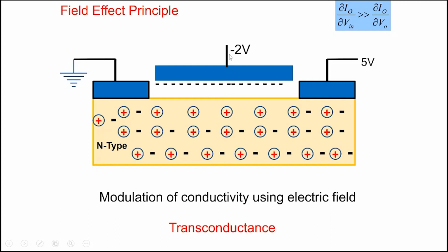And we can also see transconductance being there. The voltage is being applied between these two pairs of terminals. If we take this as a reference, the voltage is being applied between these two, and is altering the current flowing between these two pairs of terminals here, right? So the current flowing here in this particular terminal is being controlled by the voltage being applied here. That's the transconductance feature here. And of course, we need to show that for this to act as a transistor, the current flowing here should be very sensitive to this voltage and not very sensitive to the voltage over here. Then it would act like a transistor.